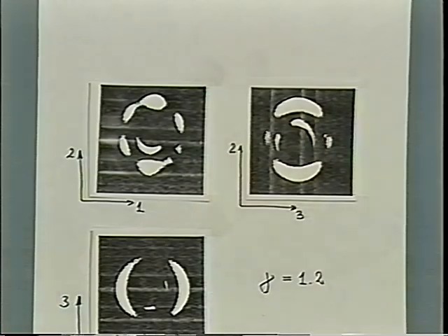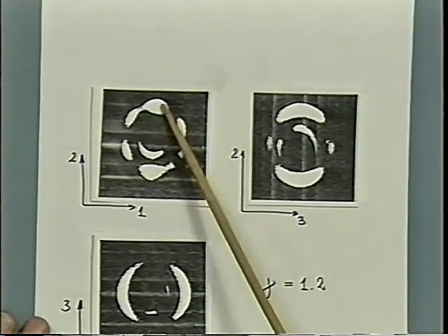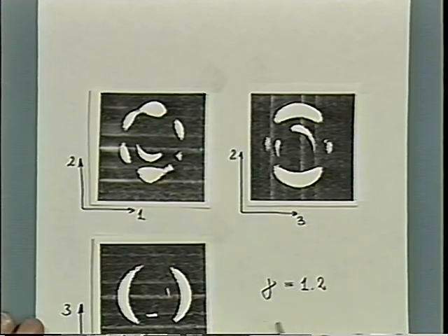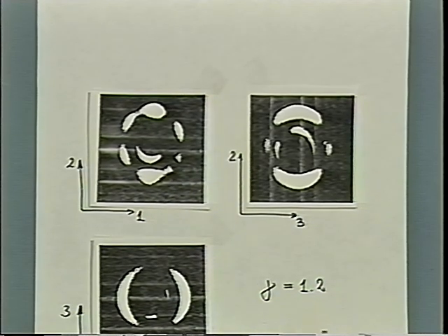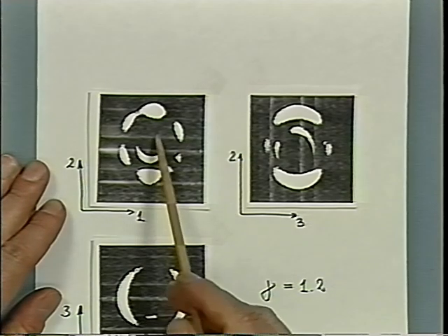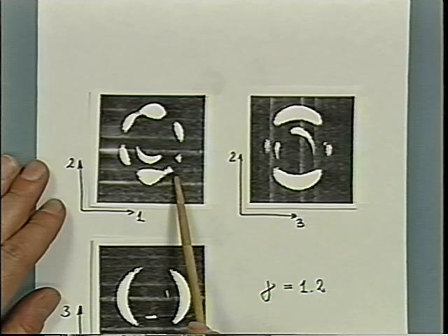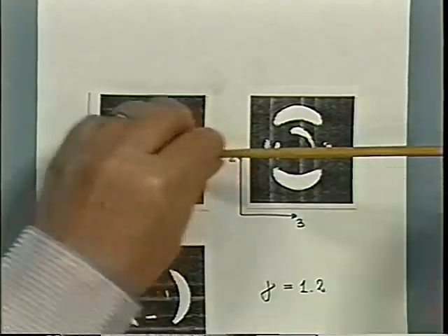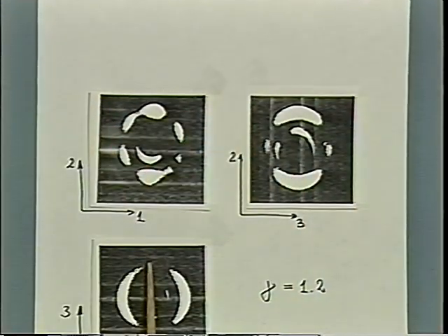This is shearing by 1.2 shear units, just a little bit of shearing. So the sample was heated up again to 140 degrees. The reflections are stronger here. I don't know whether this is just because we are shearing the sample a little bit, maybe mobilize the molecules, or maybe just heating it up again to 140 degrees and this little annealing. But I think it's the additional flow which improves the arcing somewhat. And so we still have cylinders like this. Sideways, the cylinders are aligned like this too.